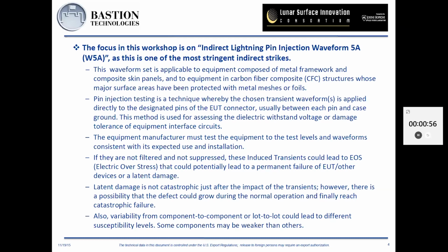Pin injection testing is used for assessing the dielectric withstand voltage or damage tolerance of the equipment interface circuit. At this point, the equipment manufacturer must test at levels and waveforms consistent with expected use and the way it is going to be installed. If it's not tested, it can create a huge chaos.